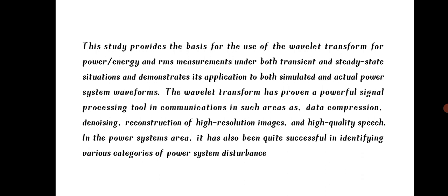This study provides the basics for using the wavelet transform for power, energy and RMS measurement in both transient and steady state situations, and demonstrates the application to both simulated and actual power system waveforms.